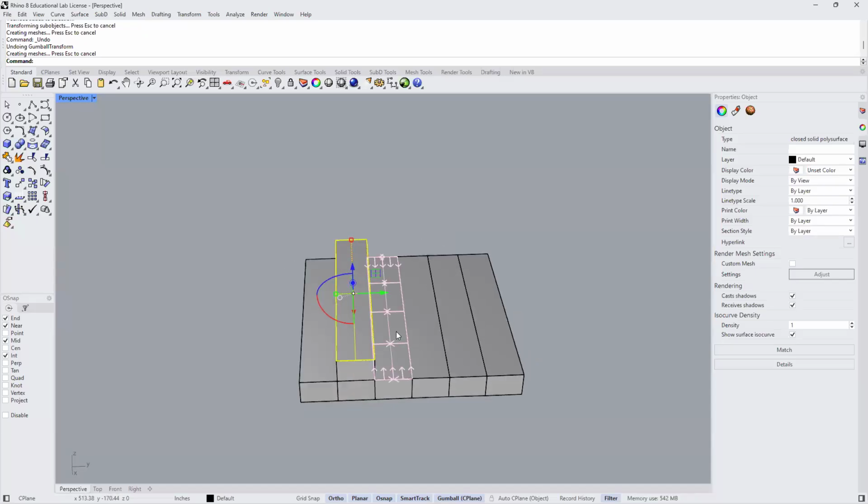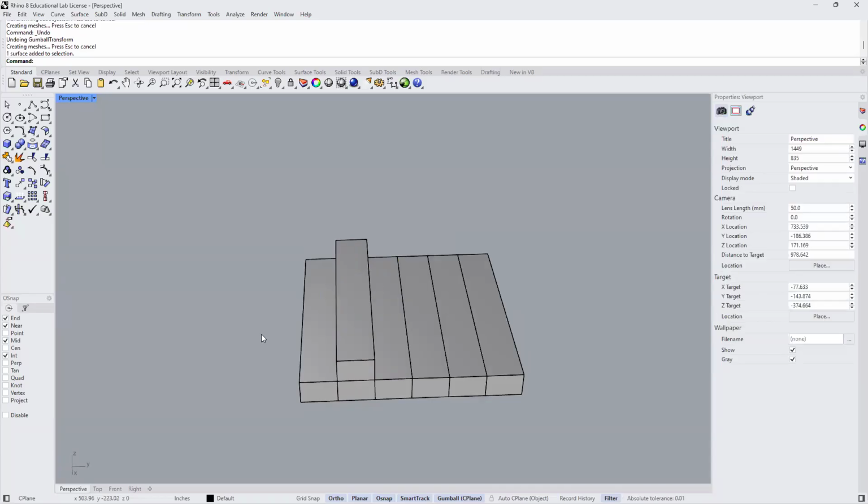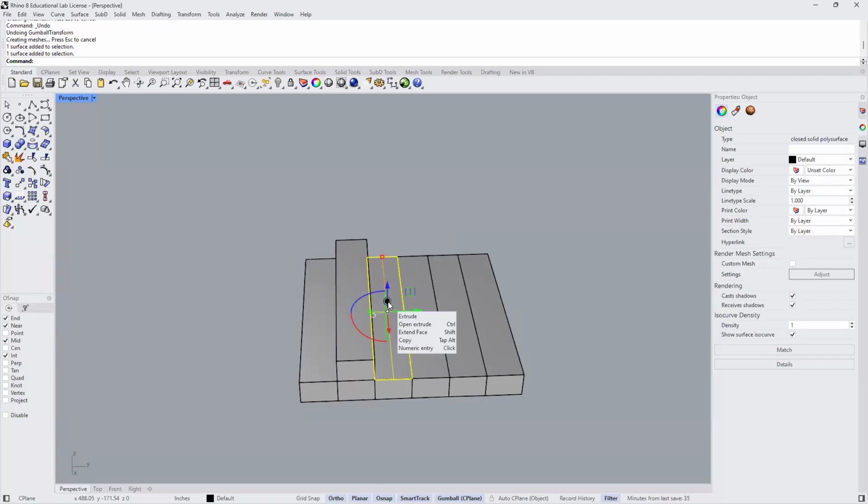And then I'll just orbit around the side over here. Hold on Control Shift, click on this surface. And notice it did not deselect the other one, so I have to be real careful here. So let me click off of both of them. Come back, Control Shift, click on this surface. Click on the blue dot. 8 plus 8 is 16, so 16 and enter.